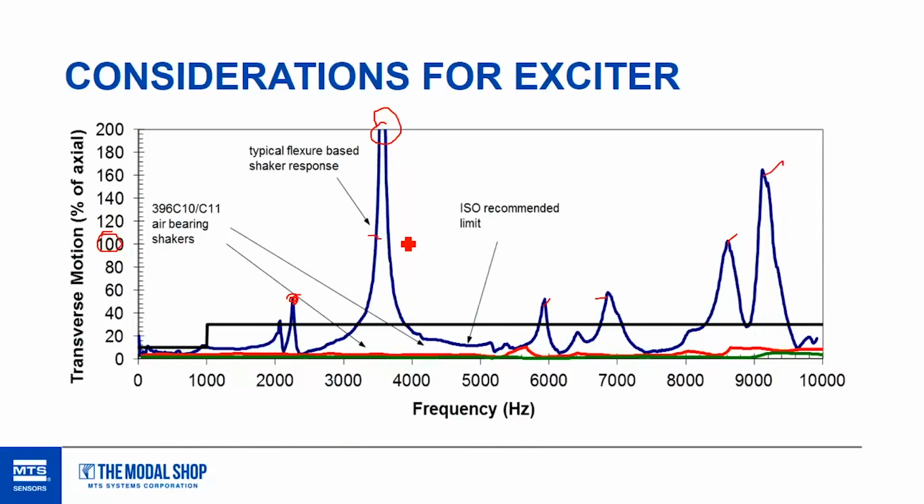And it can actually be higher, which means that your X and Y motion is higher than your Z motion. So you could have 20 Gs, or the peak is probably up here close to maybe 25 or 30 Gs of lateral motion when you're commanding your test to run a 10G sweep.